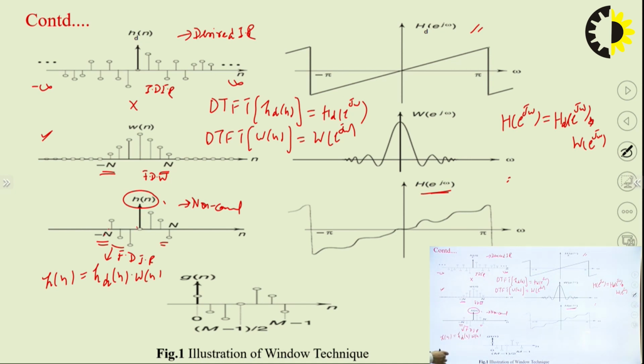Okay. So we have a new sequence, let us say g[n], which is obtained by delaying h[n] by n units in time, so that this sample will start from here. So you can see that we can make it causal. So this is the causal one. g[n] is the causal version of h[n]. h[n] is non-causal, but g[n] is the causal one.